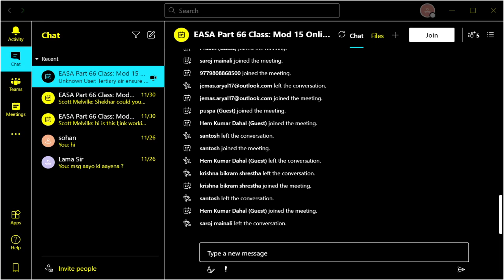Next, we're going to move on to the full flow. Very, very similar. There's not much changes to it, except there's no pressure relief valve in the system. What instead we have is calibrated jets that are calibrated for the pump output, proportional again to the speed of the engine. So full flow system, you've got what's called a metered spillback, which is always open, and calibrated, as I say, for the type of system that is there.